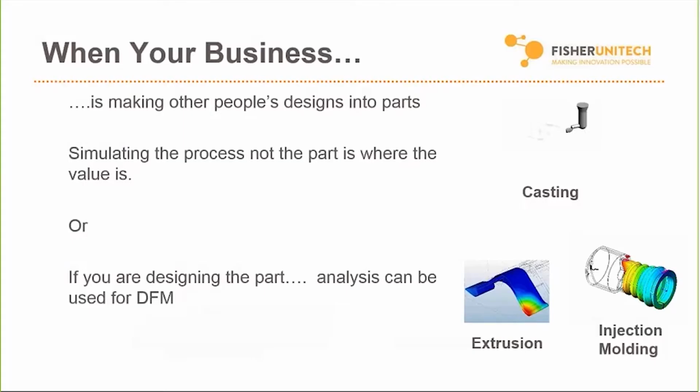So, when your business is the business of making other people's designs into parts, very often you're interested in simulating the process. So this is where injection molding analysis, casting, or even extrusion analysis, we're more concentrated on the process, not necessarily the part. However, if you are a product engineer and you are building tons and tons of die cast or extruded or molded parts, analyzing the process is very good for DFM, or design for manufacture, because we all know that the more applicable our design is to the manufacturing process, the lower the cost is going to be in the long run.